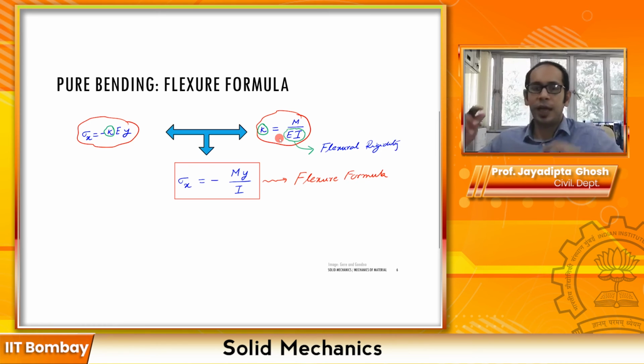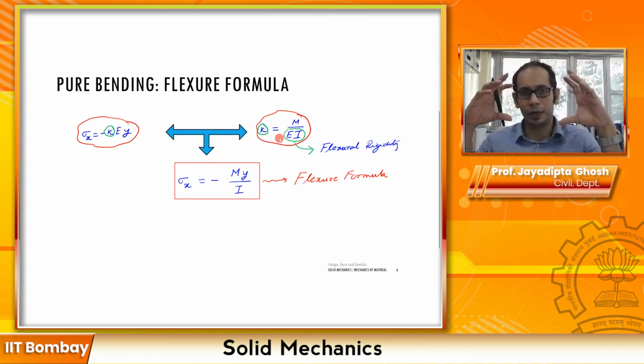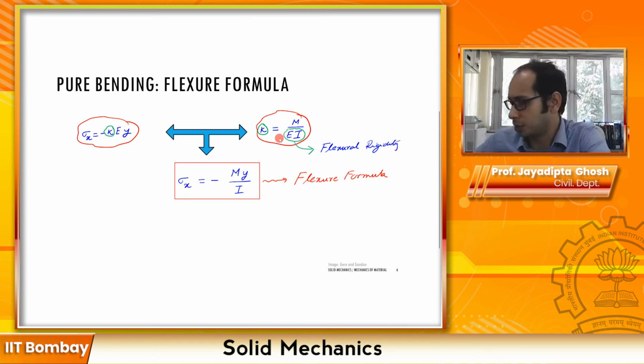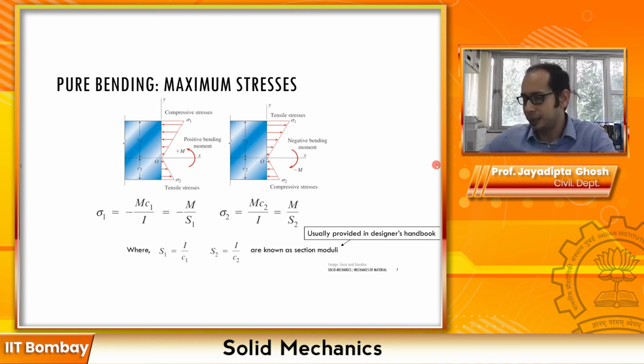So now that we have the Flexure formula at our disposal, let's go ahead and take a look at a couple of examples of how it works out. Essentially something like this. So we have, see, this is a beam. It can be rectangular, circular, prismatic. That's all. The only thing that matters is the shape of the section, whether it's rectangular, circular, trapezoid, or anything, comes into play when you compute the I, the area moment of inertia, right? And the numerator just depends on this distance.